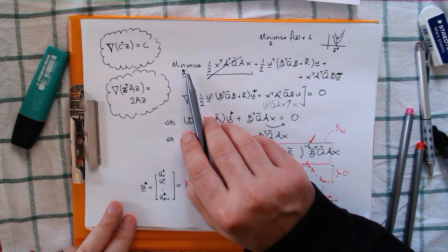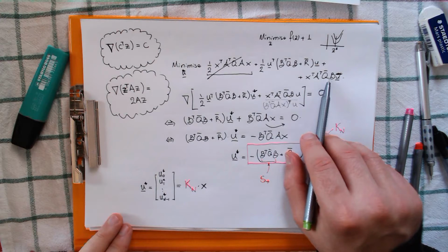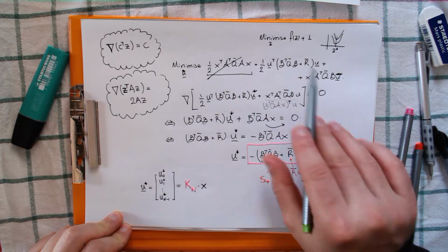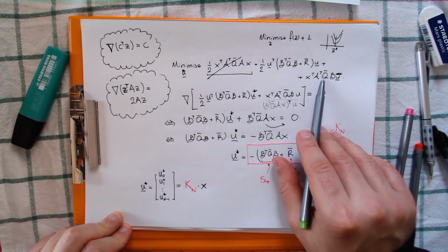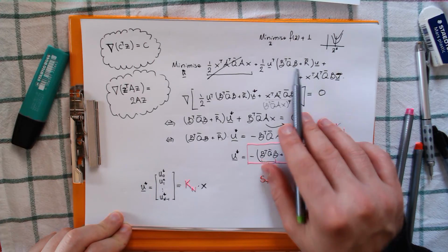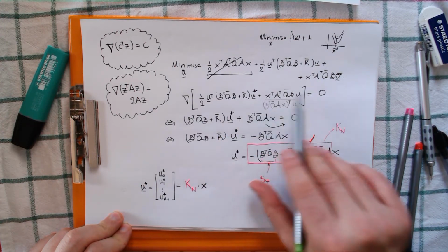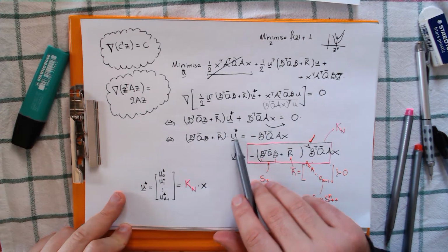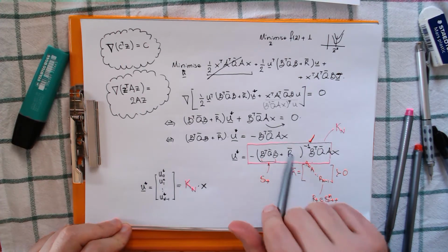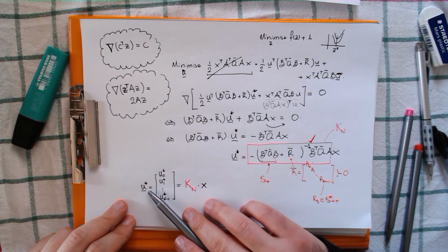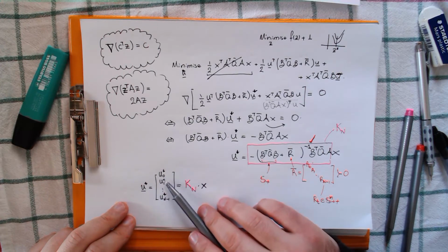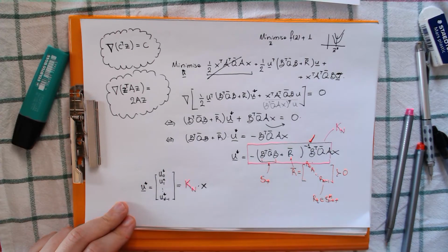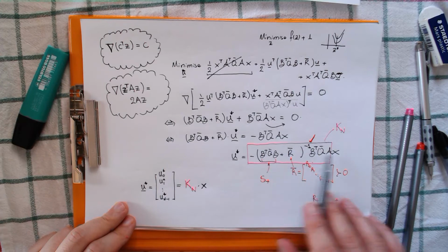We wrote again here the problem: minimize the cost function, no constraints. We got rid of the constant term and we said, okay, what do we have? An unconstrained problem. It is a smooth function, it is a convex function. How do we solve it? Take the gradient of the cost, set it equal to 0. Equivalently, we took the gradient of the quadratic function, we solved for u star, and this is the solution. And u star underlined, meaning all the control actions, u0 star, u1 star, and so on, are given by some matrix that we can compute just once.